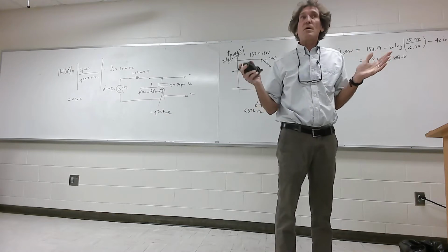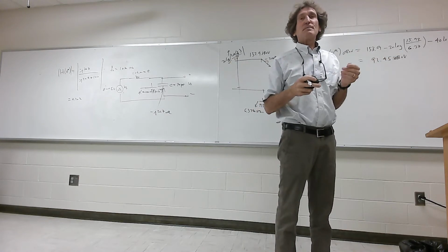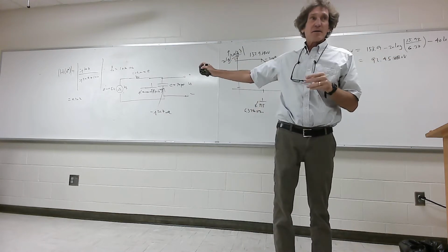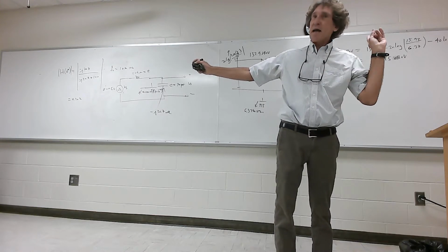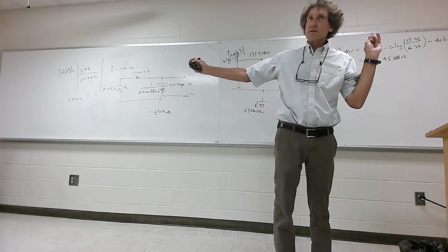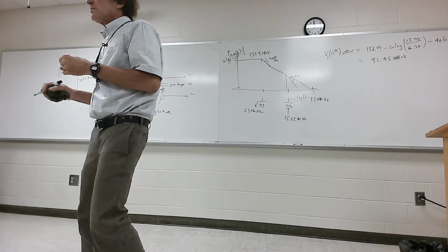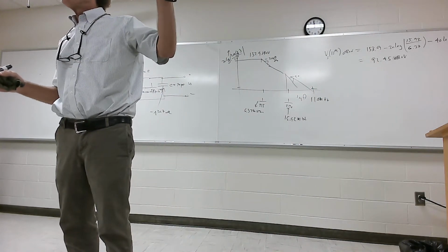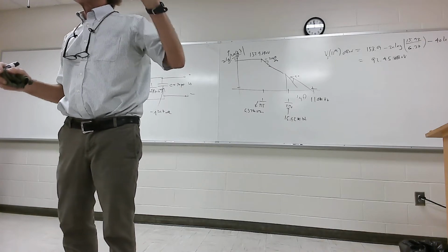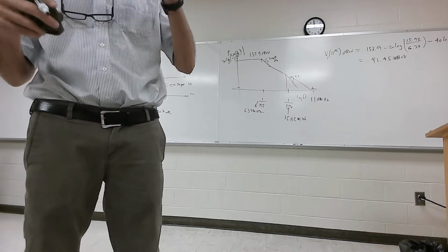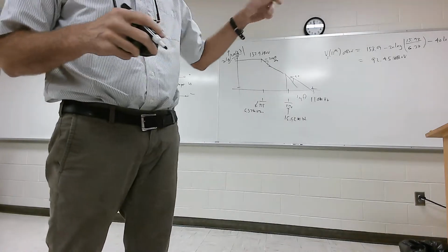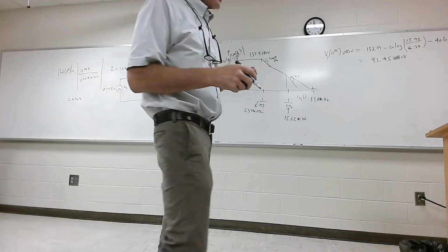By doing, what do I do now? Really, I'm just gonna take 20 times the log of that. Y'all follow me? That's all you have to do and add it to that value. Because it's the H, it's really H times Vs would be equal to V out. When you do it logarithmically, you'd have 20 times the log of Vs over 10 to the minus 6, which is exactly what we have right there, plus 20 times the log of the transfer function.